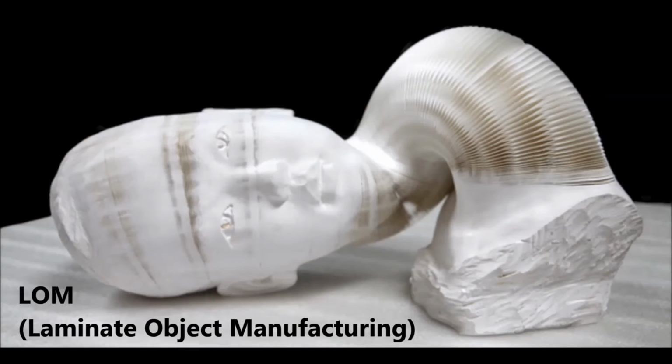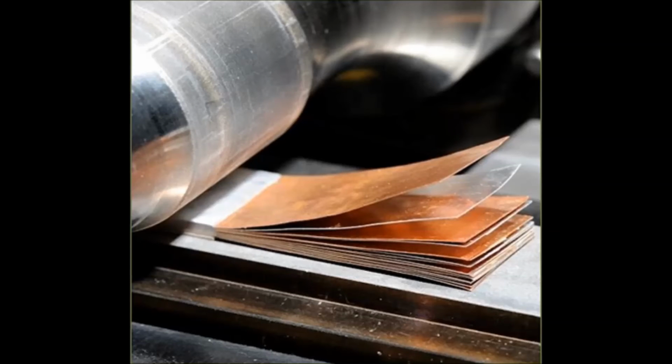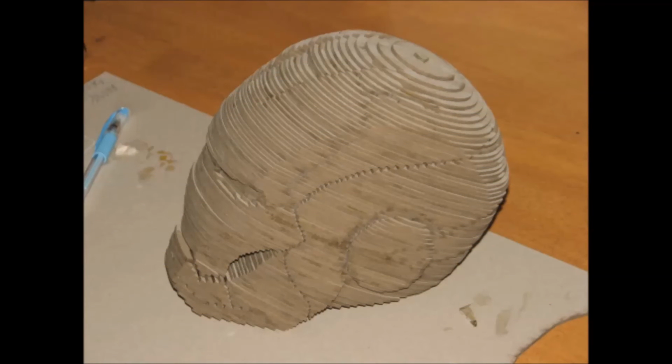LOM, or laminate object manufacturing, constructs objects using layers cut from thin strips of material like paper, sheets of plastic, or other materials. The layers of material are laminated together to form the object either before or after they are cut. The layers are usually coated with a heat-activated adhesive, and thus the lamination is done with a heated roller, whereas the cutting part is performed by a computer-controlled knife or laser.